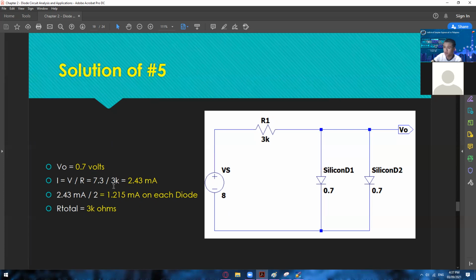So we have 7.3 divided by 3K, and you will get 2.43. But since we have two, all we need to do is divide this current into two, since we have two of the same silicon diode, and the current will split equally. So 2.43 divided by 2 is 1.215 milliamp on each diode. And then the R total is 3K ohms.